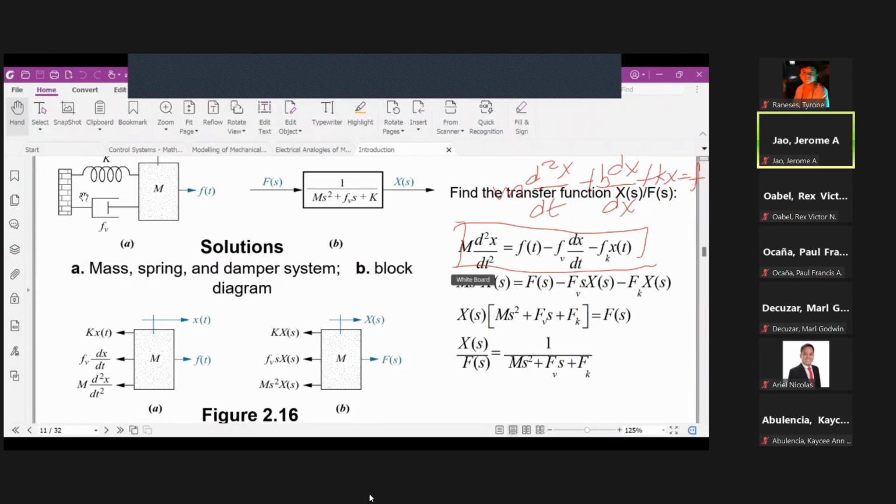So when we want to know the transfer function, we said let us first transform your differential equation model into what? Laplace transform. If you remember, how do we take the Laplace transform? This M becomes big M. And since this is second order, how many s? It is s squared. So here it is. Is that right? Then it is a function of X of s. This one, x. Do you get it? Do you remember? Yes, sir. So this F, this is the output, no, the input. Earlier it was F of t, so it becomes F of s.